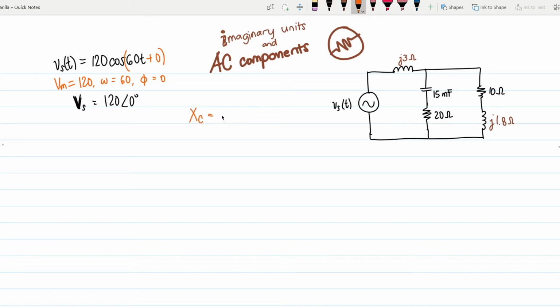So this is where a lot of people, including me, I remember that time, got confused. I just wrote down, because I already knew that capacitive reactance was going to be negative, minus j omega C. This is wrong because the original one is just 1 over j omega C, which if you want to rewrite it with negative j is going to be negative j over omega C. So big wrong. Do not do that. And so let's just follow our formula for now.